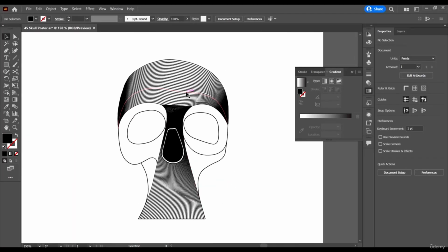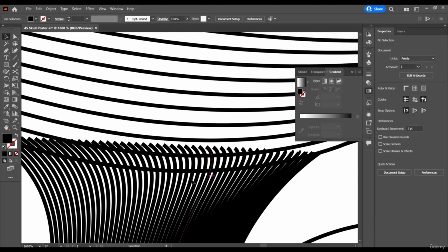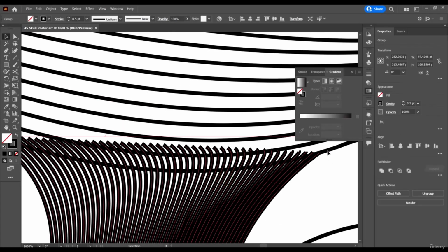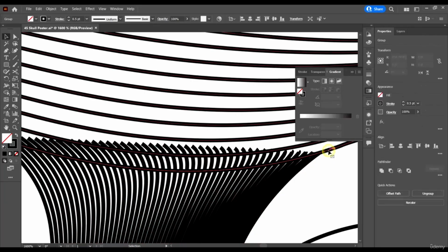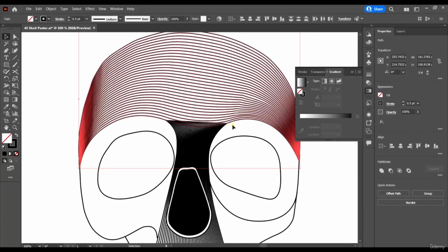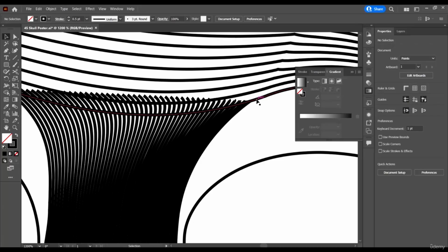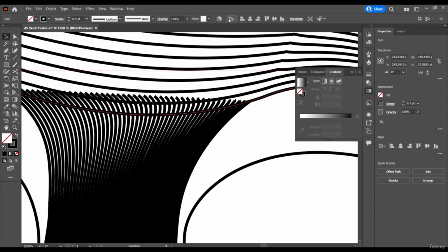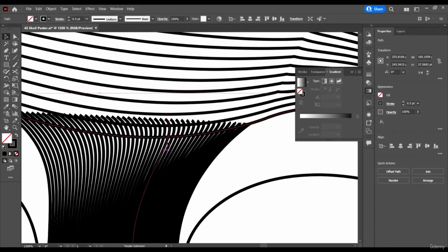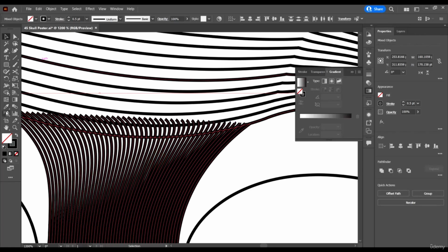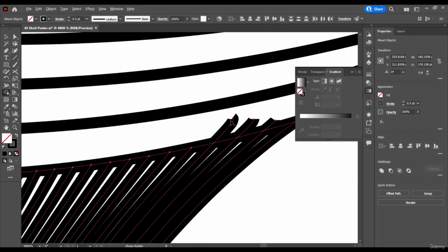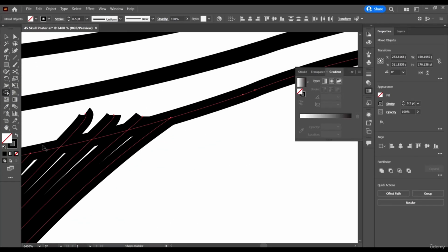Okay. And then we now work on this one. So select your shapes. Select this guy here. And maybe we want to just ungroup this one, so we can just select this very one without having to select every other part of the group, right? So select this line and select these ones, and go into your shape builder tool and holding down Alt, you can now drag, and as you can see, it's now cutting the lines from here, right?